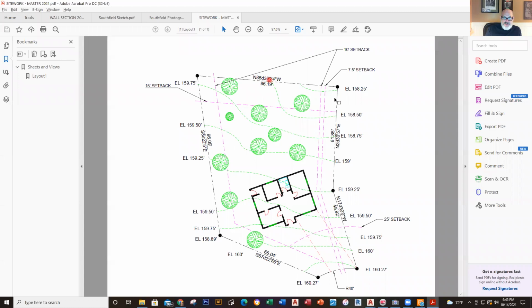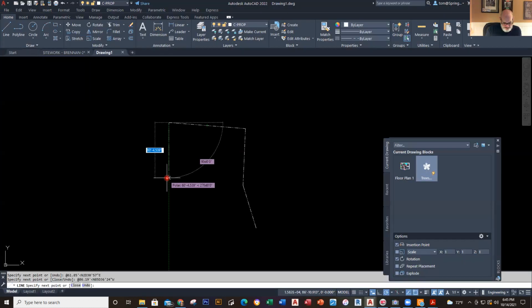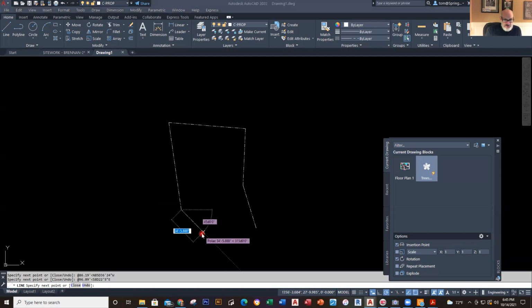And so I got this. So I just did this. So I did 1, 2, 3. Now it's this one. This is 96.09 feet south, 8 degrees, 22 minutes, 5 seconds east. So I go ahead and put that in there. So this one is going to be 96.09 feet less than south 8 degrees, 22 minutes, 5 seconds east. There we are. Okay, so it's coming along here.